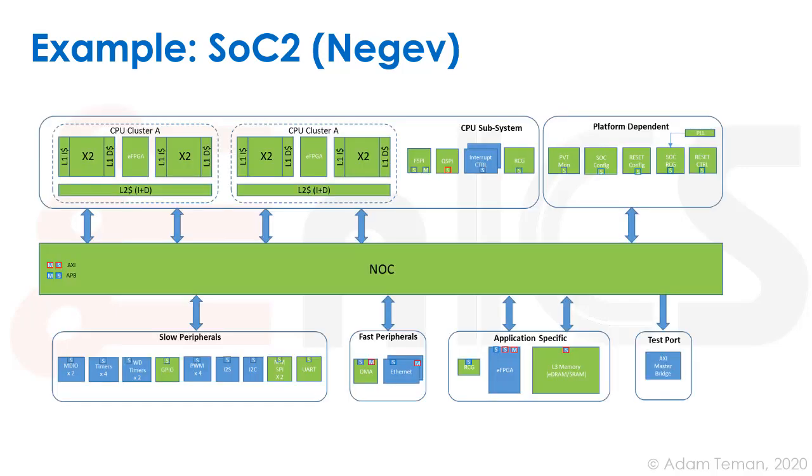So with the chip, what we usually do is build an architecture, and this is the basic architectural block diagram of the chip. If you look inside, you can see these X2 blocks. These are DSP cores, a type of CPU core. So there are 4 of these microprocessors on the chip. Each one of them has a separate data and instruction memory, or what we call a level 1 cache. Each cluster of 2 has a level 2 type of cache. And then we have in different places all kinds of other things.